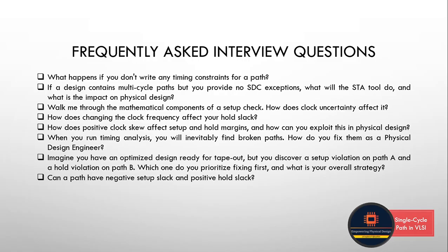Now, how does changing the clock frequency affect your hold slack? Well, changing the clock frequency does not affect the hold slack. We have seen that in today's video, right? Hold time depends entirely on data path, not on the clock path. Always remember that hold time depends entirely on data path delay and clock skew between the launch and the capture flops, not on the clock period or frequency.